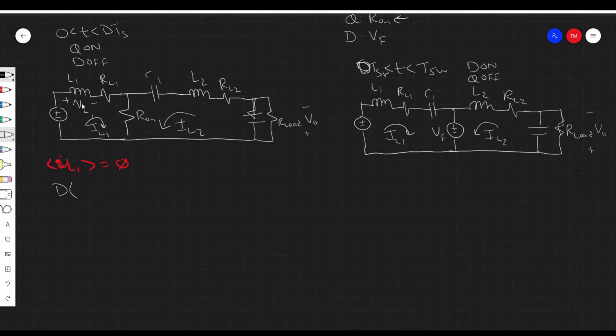So the voltage across VL1 is equal to VG. We have a voltage that is anti-parallel to our loop, so we subtract IL1 times RL1. Again, we have a voltage across this resistor R1, which is anti-parallel to our loop, and it actually has two currents flowing through it, right? It has IL1 and IL2. So we subtract off IL1 plus IL2 times R1, right? And that's the voltage. We just consider this loop.